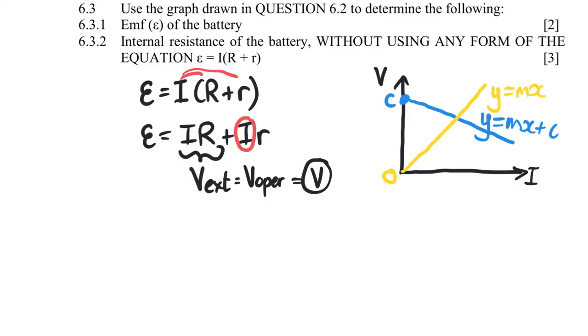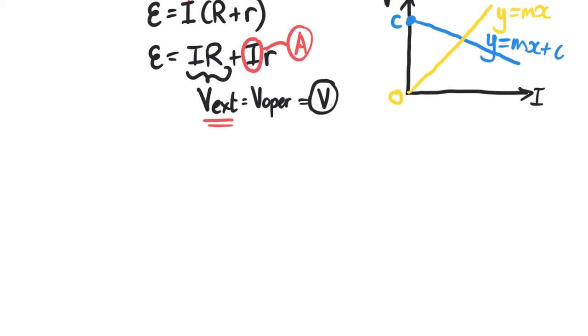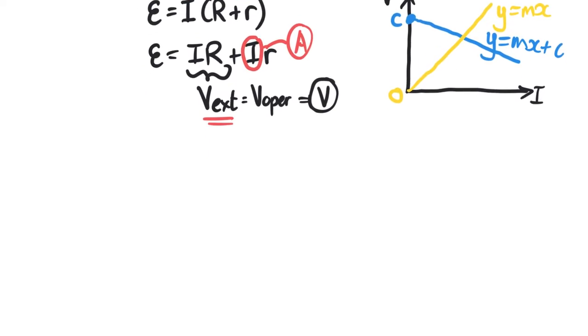This is the total current, and that's the ammeter reading. So what we're going to do is make V the subject of this equation. I'm going to do it by taking this across to the other side. So we're going to make that minus Ir, little r, plus the EMF equal to V, external V. I'm just going to call it V,